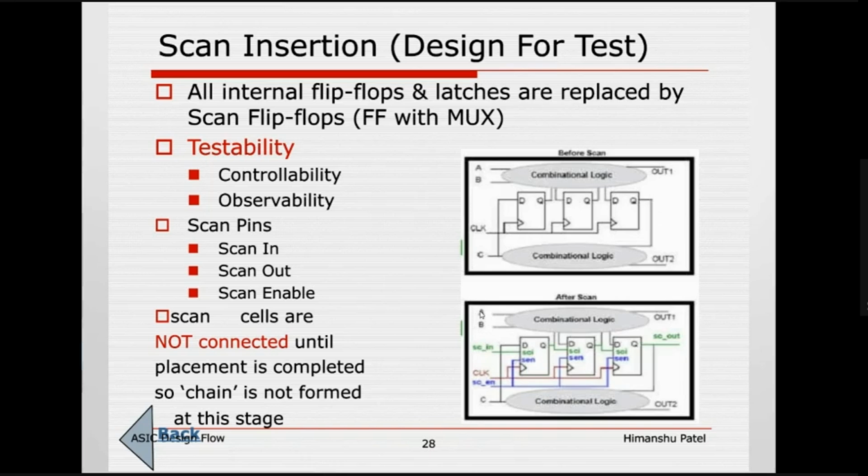Just think. There is an AND gate input and you want to prove that it is not stuck to ground or stuck to high, and now we assumed that we want to prove it is not stuck at 0. What input will you give to that particular port to prove that it is not stuck at 0?